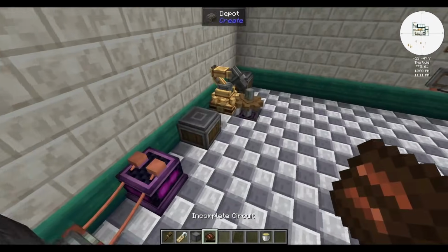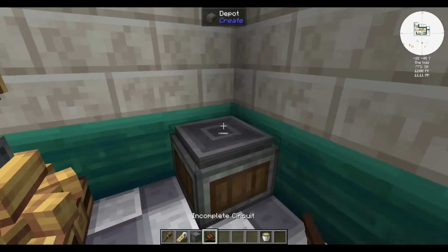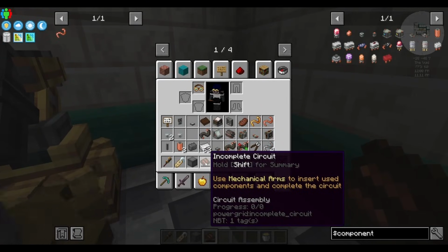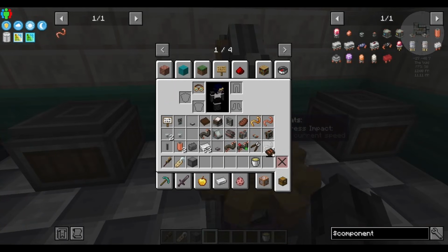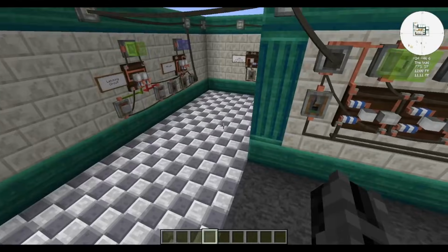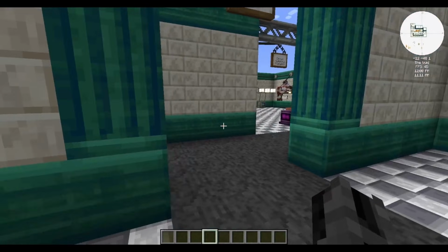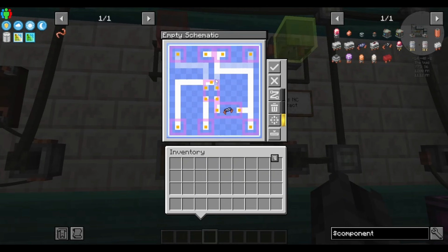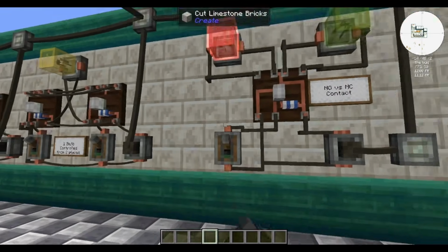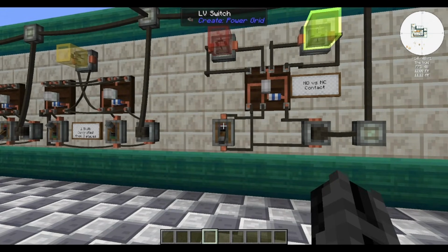After you etch your circuit board, you may put your components on it using a mechanical arm. This one has no components, so we cannot put anything on it, but that's how you do it. Okay, so what can you do with these, aside from smaller voltage dividers? Well, the simplest and most useful is a relay. It works as an electrically controlled switch, which has two contacts, normally closed and normally open, which allows you to switch between two outputs. Here I have a red and a green LED, which is controlled by this lever.